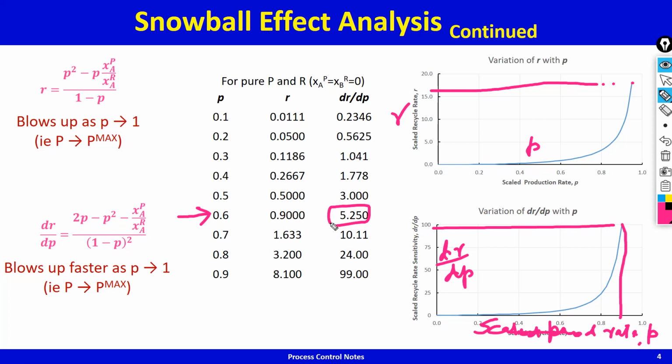Distillation columns are designed at the nominal steady state to have a boil up that is 80% of the flooding boil up, or the vapor superficial velocity through the column is 80% of the flooding vapor velocity.